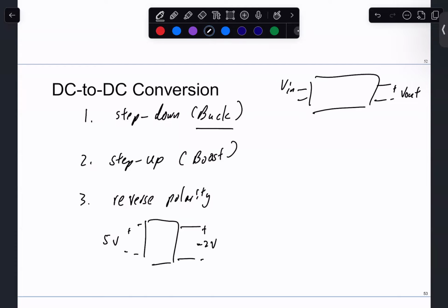A lot of the older technology, if you look at all the cables, there's only one way you can plug in a cable. So that's fixed polarity. And this is called a buck boost converter. We sort of run out of names here, so let's just say buck boost. Buck boost will flip the sign and may do some voltage conversion after a fixed sign.